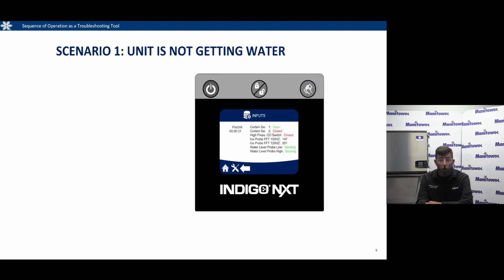All right, so scenario 1, said we'd get to it. We're getting to it quick. Unit's not filling with water. Here you see, we're in pre-chill. That's hours, minutes, and seconds. We're 31 seconds into pre-chill, and you notice there's no water in that pan.